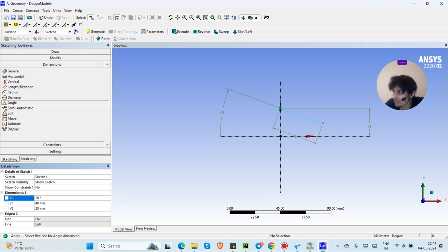I'm wondering. Create the blade sketch continued. Let's take some time over here. Select the x-axis, right click and select alternate angle until the correct angle dimension is shown, then click to position the dimension.